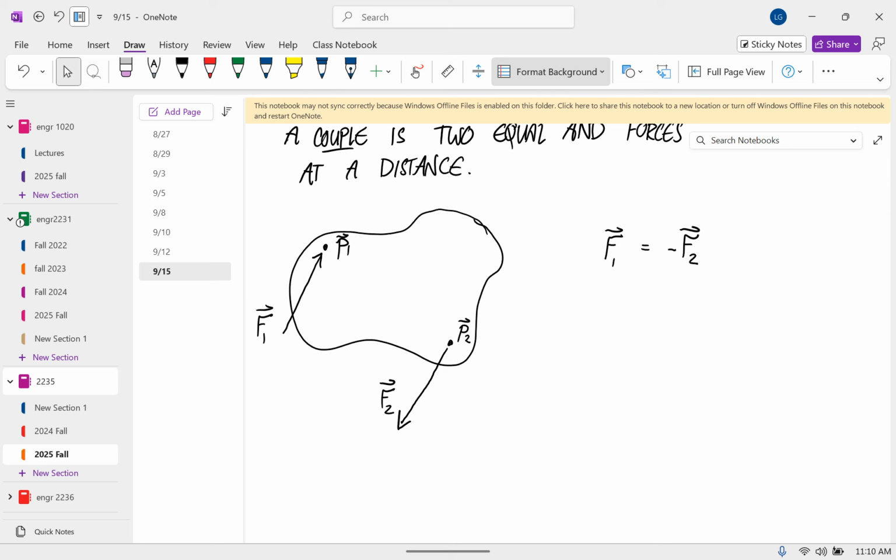Yes. So, like you said, they make rotation. Are they perpendicular? If you draw a line between them, does it need to go through that? No, it doesn't have to be perpendicular. They can be anywhere. And does that also work in 3D? Yeah. So they only have to be the same magnitude and different directions? Opposite directions, specifically opposite directions. It can't just be this way and this way, or whatever. They need to be equidistant from the about point? No, they don't. I haven't even defined an about point yet.